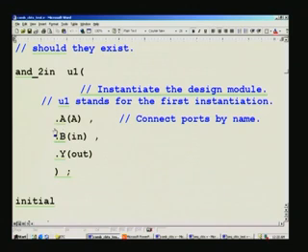The advantage is you can put A at the last or in between or anywhere. It is very easy for us to remember names rather than the order in which we wrote them. If it has 20 or 30 signals or even more, you get drowned in which order you had mentioned in the design. You will most probably make a mistake and change the order, and if you change the order, the whole thing will be chaotic.